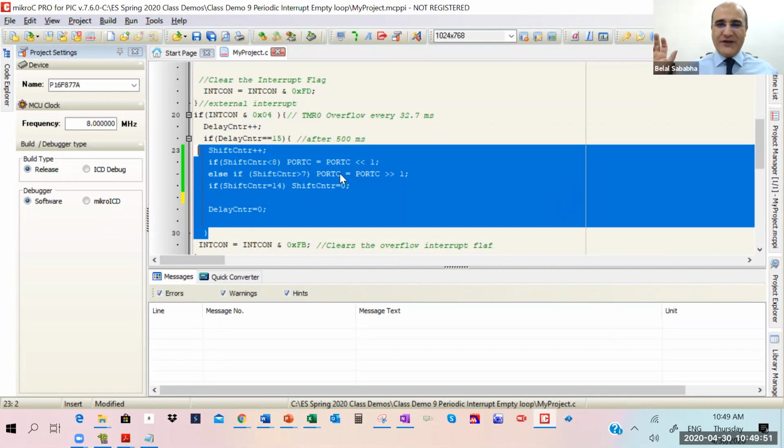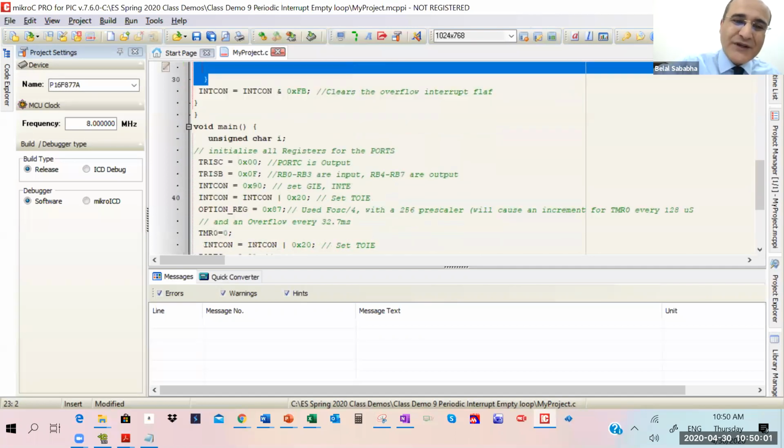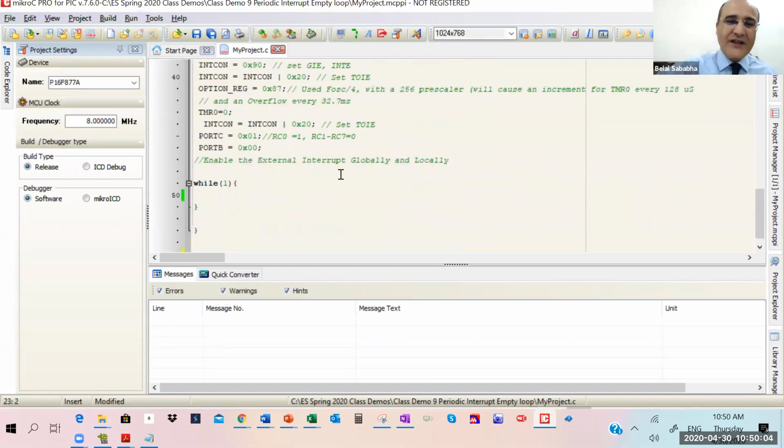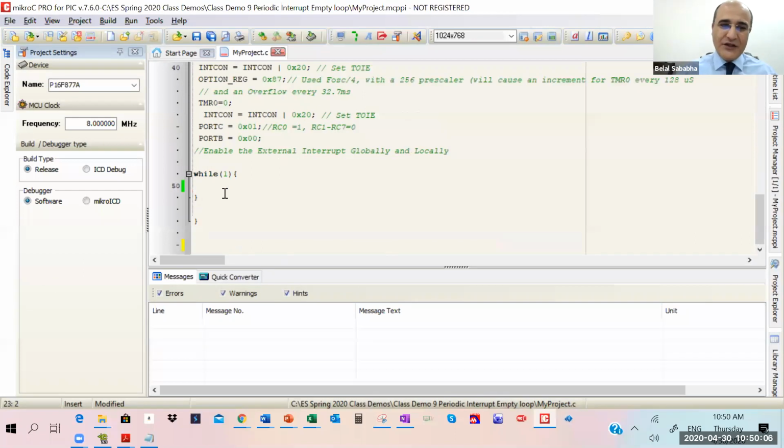Right, 10 out of 500. Yeah, let's say 50 milliseconds. Out of 500, you're 90% of the time free. You can add much more tasks here, critical tasks, or anything else to do.